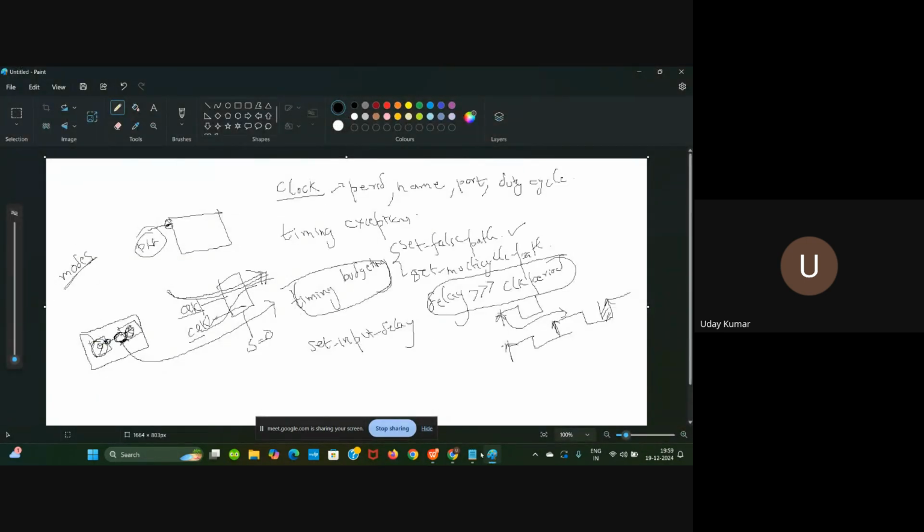So I'll get these delays. These are called asserted delays, and I'll get this on this port. Now my tool will be able to calculate it as an edge to out path, and it will have the delay here also. But now I'm asking a question: how will the tool know on which clock edge I need to check? Because the capture flop is not inside my block. The capture flop is somewhere outside. So how will the tool know that?